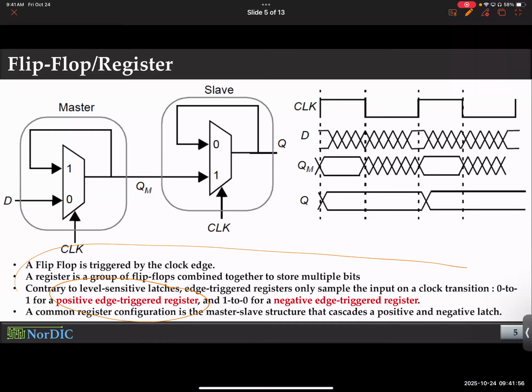Great question. Yes. So since sequential circuit, as the name suggests, deals with sequences, timing diagram is a very big deal. You have never seen timing diagram for the combinational logics, did you? For n gate or gate, there was a truth table, which was the boss, right? We always had to look at the truth table because there was no concept of any sequence. As long as there is a combination, you have a certain output. But this is not just dependent on the combination, it also depends on the history. So timing matters. What happened in the previous cycle? What happened in the cycle before it? So that's why this timing diagram is definitely the most important part.